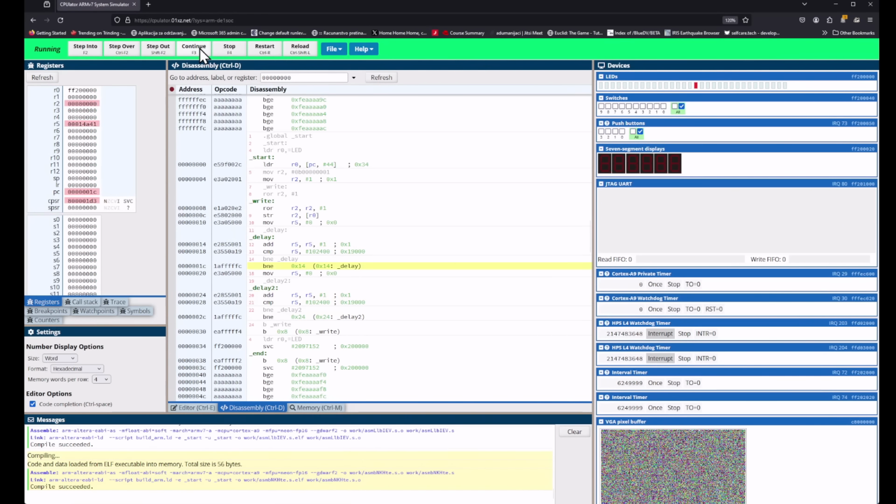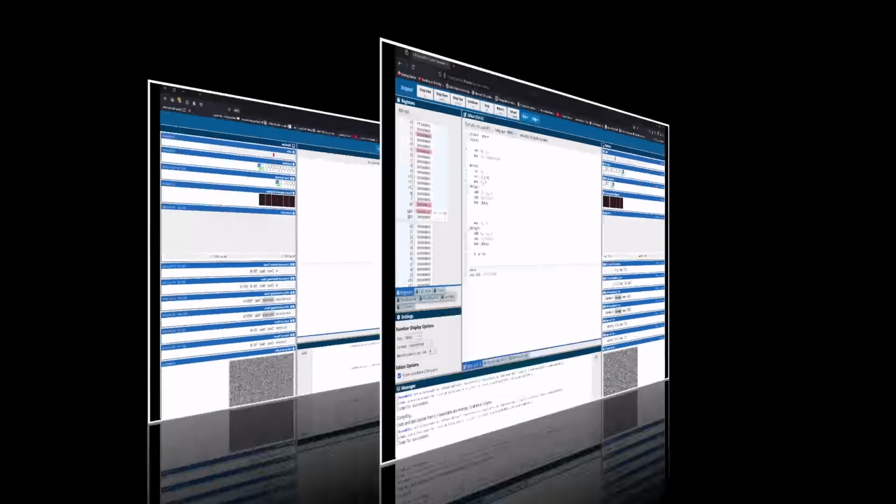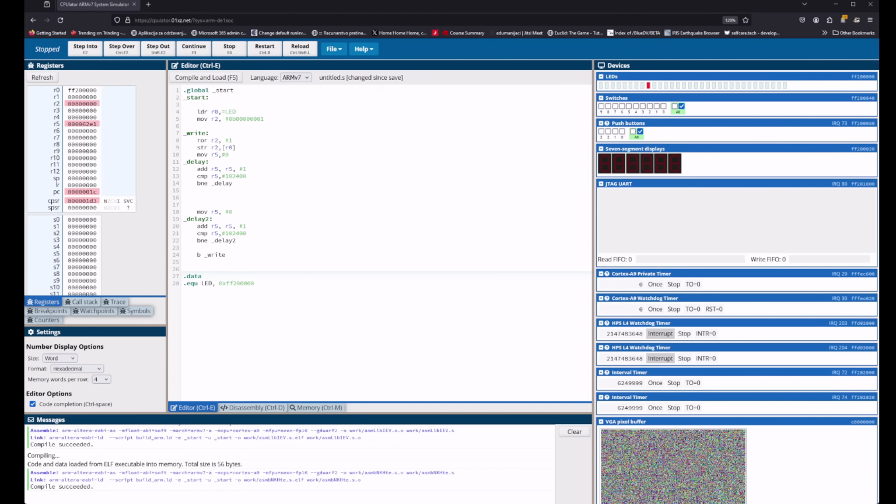Let's try to continue. And now I actually managed to show how rotation works in the 32-bit values that I'm using as a reference. Also note that this is so quick that I'm actually doing 2 delays. I'm rotating, showing the LED, creating a delay, then creating another delay, and then I'm stepping up, and it still rotates extremely quickly. If I remove all the delays, you probably wouldn't be able to notice. It would just blink completely randomly, based on how quickly the thing is able to do. The last thing I did was the delay and the rotate to the right.